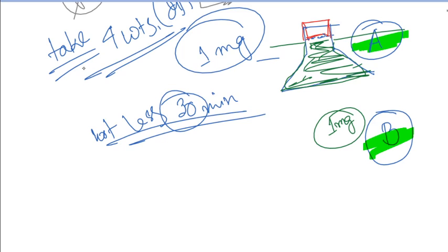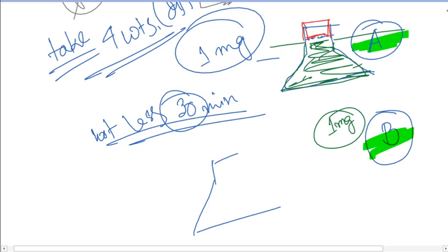What we need to do after that is pour the bituminous materials into this pycnometer. But before pouring the semi-solid bituminous material into this pycnometer, we need to again remove all those waters and make this pycnometer dry.